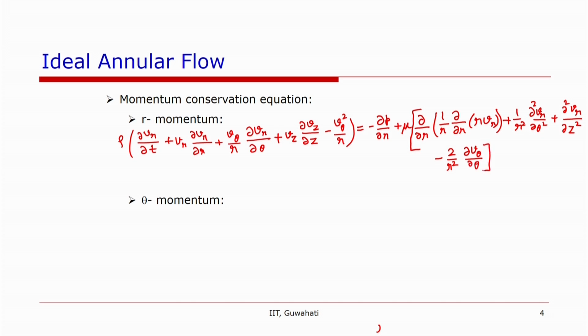We do not consider gravity, so the gravity effect is not considered. If we take horizontal flow, then the flow will not be axisymmetric if the gravity effect is considered. But remember that in a micro channel, where the channel size is sufficiently small, the effects of gravity are anyway negligible.